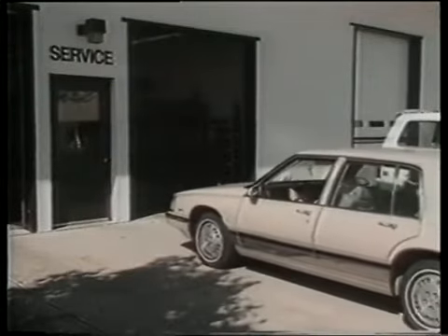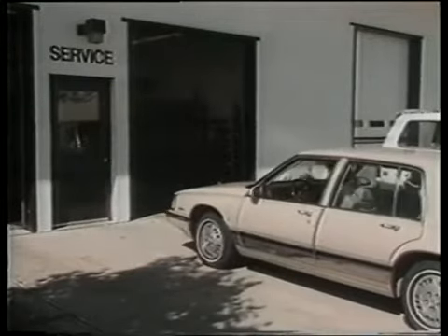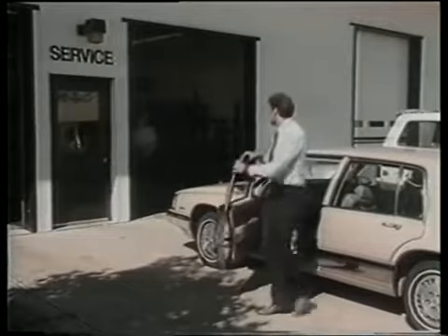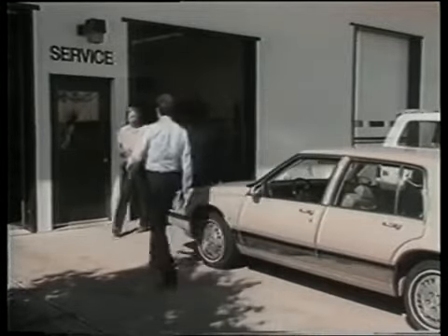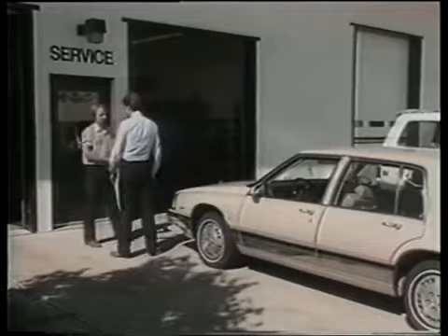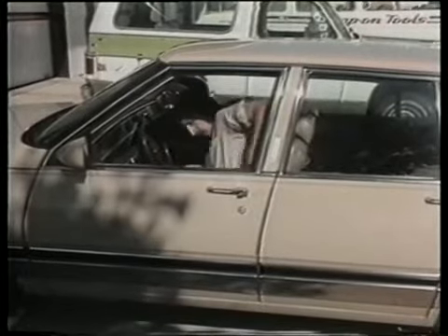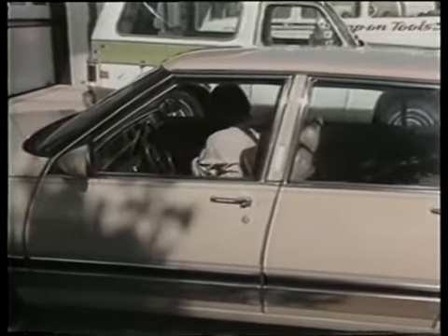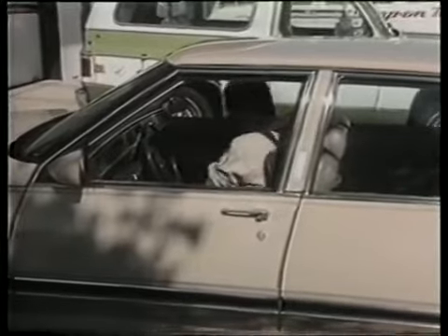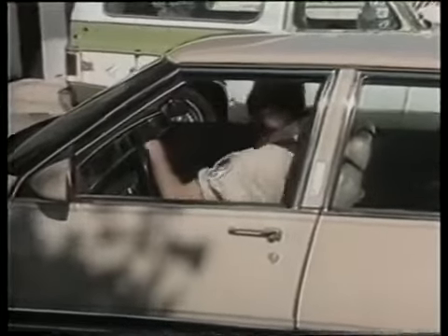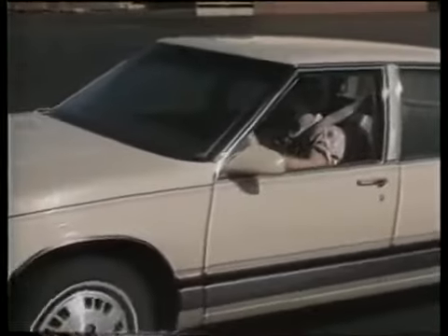The first step in troubleshooting an EFI system is to gather information. Talk to the customer if possible. Find out what he or she thinks is wrong with the performance of the engine. Then test drive the car yourself to make your own conclusions about potential problems. Quite often, the customer's description of the symptoms will be vague and even misleading. During the test drive, try to simulate the conditions when the problem occurs.